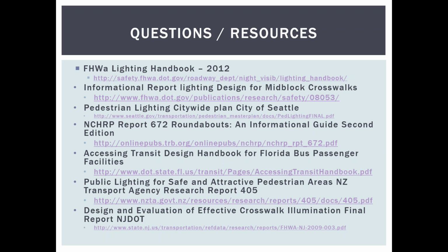The one thing I have to caution you about is if you develop standards or a policy, then you have to adhere to it, because it could be used against you in a court of law. So it is good to create these types of standards and work towards improving lighting levels. I think going with what the IES has is probably the better guidance. As we talked about for the crosswalk and crossing areas, 2-foot candles of vertical illuminance, or 20 lux, is what's recommended for crosswalk areas.